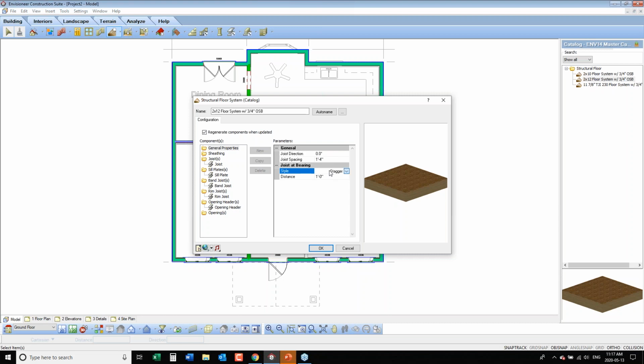And when the joists hit a bearing point, when I tell it that there's a beam coming through, what happens to those joists when it crosses over that beam? Right now I'm telling it to stagger, overlap by 1 foot along that beam. Or I could tell it to hold back. So if I was using hangers, as it came up to that beam, it would hold itself at that beam so that you could have the different layout for if you were using hangers instead.